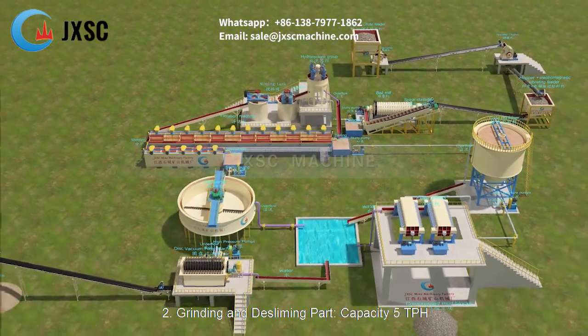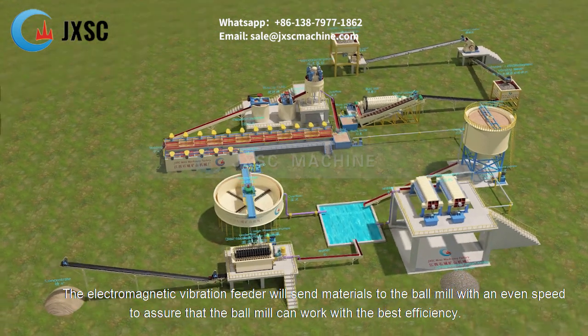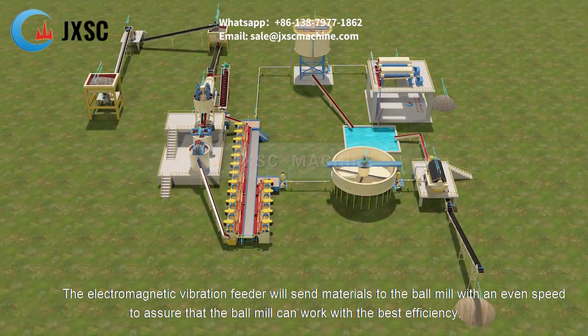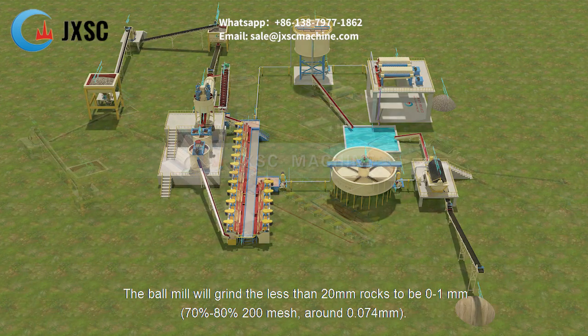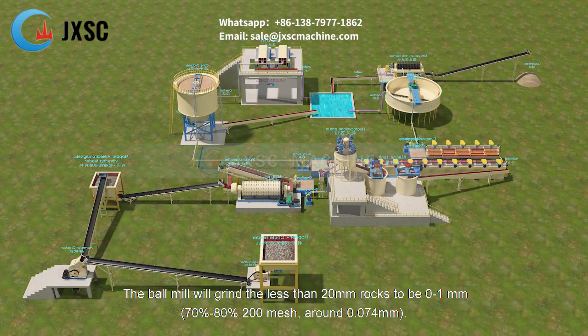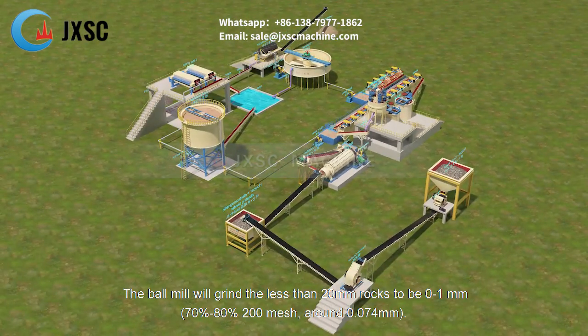2. Grinding and desliming part, capacity 5 TPH. The electromagnetic vibration feeder will send materials to the ball mill with an even speed to assure that the ball mill can work with the best efficiency. The ball mill will grind the less than 20 mm rocks to be 0 to 1 mm, 70% to 80% 200 mesh, around 0.074 mm.